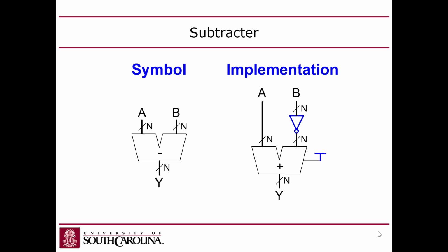Make sense? Now, when I used to see this, I used to say, wait a minute, that requires 2 adders. But it doesn't, because you can take advantage of the carry in input on the adder. It's kind of like regrouping these. So it's a plus not b, and then add 1 through the carry in. This symbol is meant to show a hardwired 1. That's a VDD symbol.